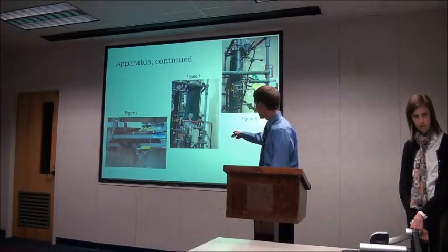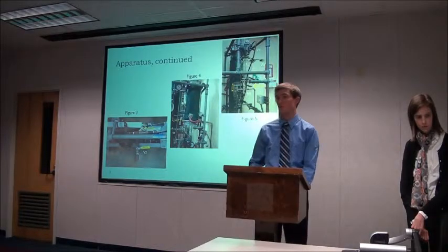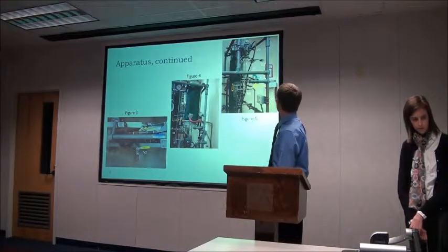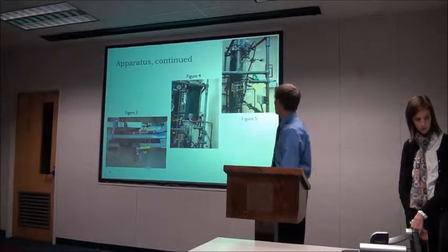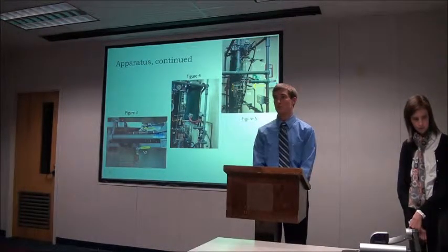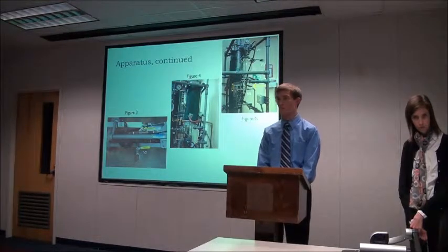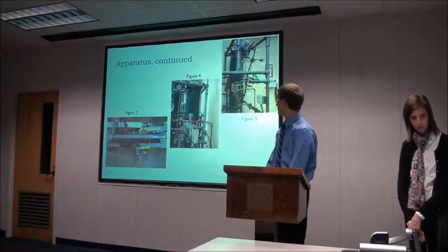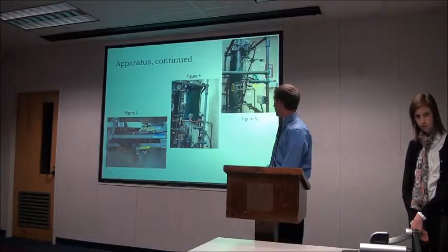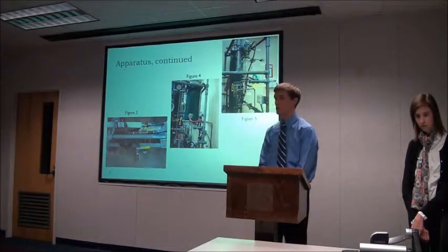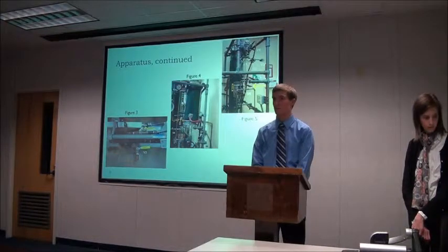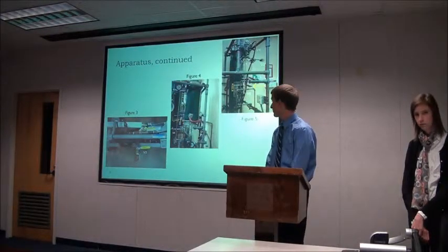So we would close valve 6, which was open to the atmosphere, valve 3, which was open to the atmosphere, and valve 5 we would keep closed until we needed to collect the liquid from the condensate over in figure 4. Whereas figure 3 we could just leave constant because it was already open to the atmospheric pressure.